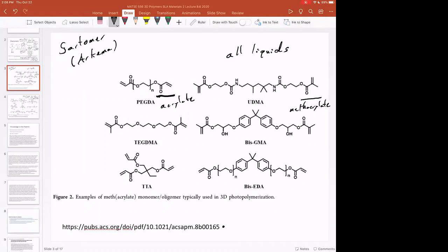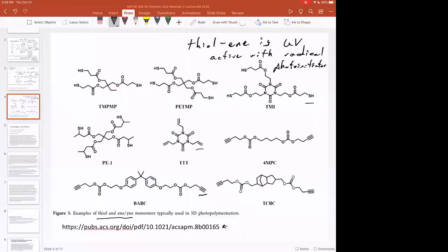Primarily, acrylates and methacrylates are the dominant chemistry, but some other photopolymerization chemistries are starting to come to the fore, like photo ROMP or photo ring opening metathesis polymerization. There's some photo Michael addition polymerizations out there, but those in general aren't deployed in industry yet. They're too slow. They take a lot of light. And so remember, for SLA, in general, you have to have very fast reactions, and you have to have good photo curing behavior before it can be deployed in the technology.